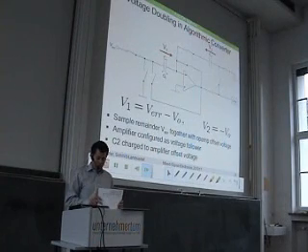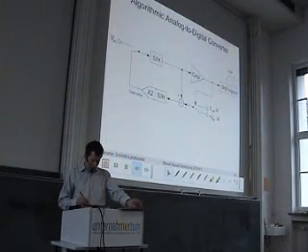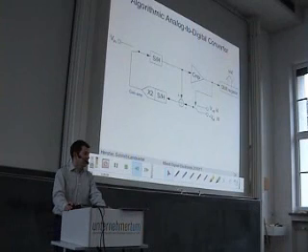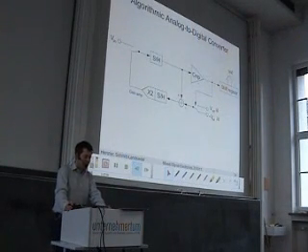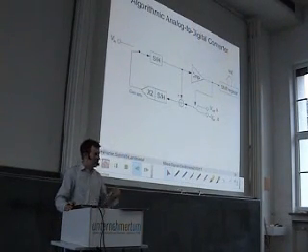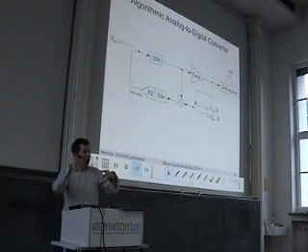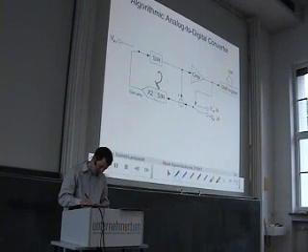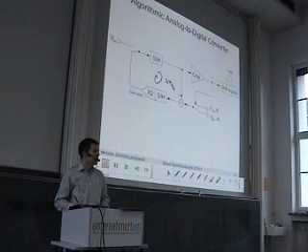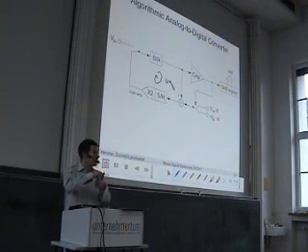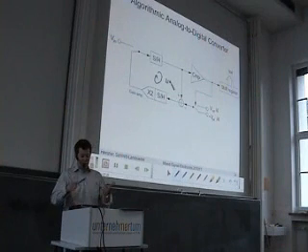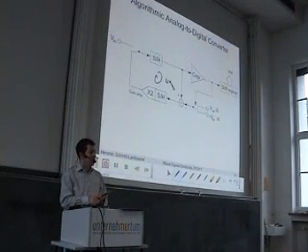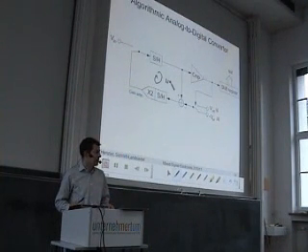Next week we will continue with this, and we will start with this block diagram. Because the main drawback that we have in this circuit is that we have to sample the voltage and then we have to do n cycles. So we go around here n times. And of course this takes a lot of time because we have to do n times the comparison, n times the plus minus Vref over 4, n times the x2.